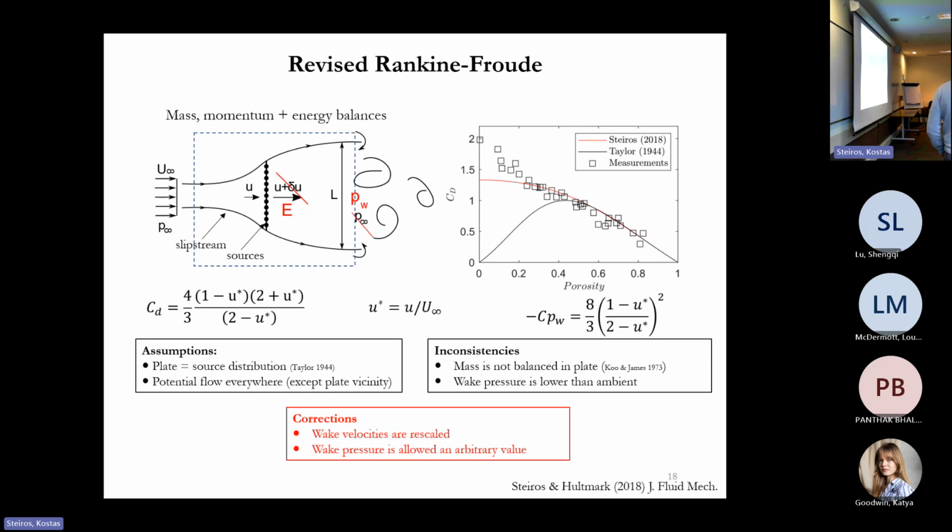However, there was still a discrepancy between the prediction and the theory, unrelated, of course, to the application, but I decided to go the extra mile and try to understand what is happening, what am I missing in my modeling approach. And then we might remember from our basic aerodynamic studies that very solid bodies create a phenomenon that's called vortex shedding, the shedding of coherent vortices. But what they do is they lower the pressure even more, and they increase the drag of the object. When we go to high porosities, these vortices do not appear, so we don't have to model them. But at low porosities, they exist. Now, of course, the model here is potential flow. It's quite simplistic. It cannot model this kind of very complex instabilities, right?